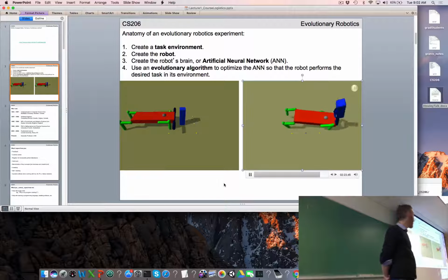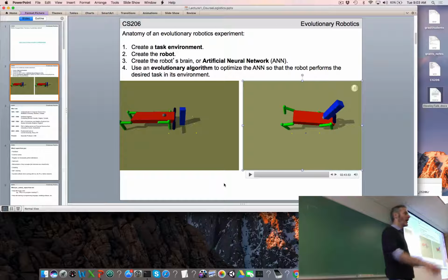This is kind of a subtle thing. Why? Now again, I haven't told you all the nuts and bolts of this experiment. Is that just the weight distribution of the robot? It's the best way it can walk in the environment? Possibly. So we're going to spend a lot of time talking about legged locomotion and bipedal locomotion. When you run, you pump your arms in opposition to your legs to cancel torque about your long axis. It might be that doing that helps the robot stay balanced. It's not quite clear in this experiment. That might be a reason.